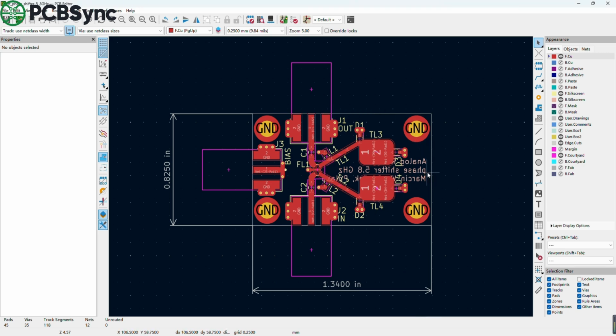This is an open-source distributed phase shifter operating at 5.8 GHz. J2 is the input port, J1 is the RF output, and J3 is used for bias control. TR1 to TR4 in the middle are transmission line structures. Their width and length directly affect impedance, electrical length, and phase.